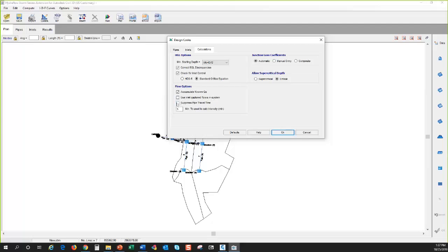It's nice to have this option, but I'm having a hard time seeing when I would do this. The pipe travel time is an important part of the calculations, and so I would want to consider it. I guess if you didn't consider it, it would be somewhat more conservative, but I think in most cases it would be kind of inaccurate. So I leave this unchecked.